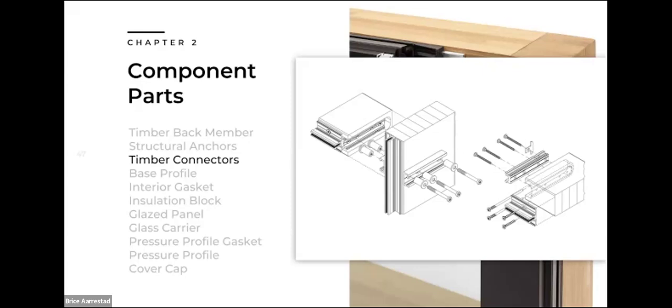All of these components, like I said, are attached in the factory. So the mullions receive the male parts, the transoms receive the female parts, and they're attached in the factory. So all of the routing, all of the cutting, pre-assembly happens in the factory.